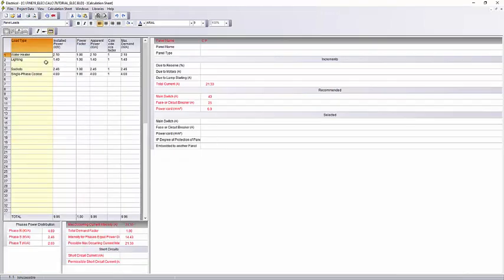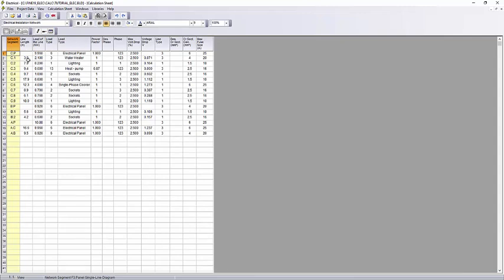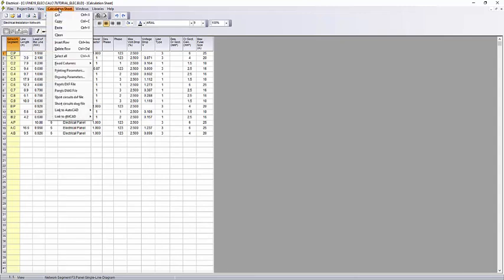Based on the data entered in the calculation sheet, all data are automatically calculated for each panel separately. To return to the calculation sheet, you should press F7 again. From the calculation sheet, we can export the panel and short circuit segments to DWG or link them automatically to AutoCAD or 4M CAD.